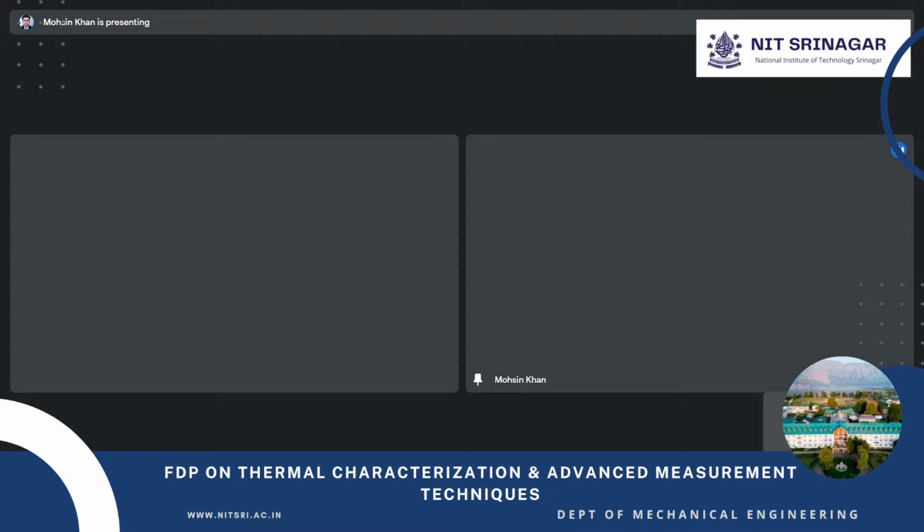This step shows the mechanical stirring, where essentially we use mechanical stirrers or magnetic stirrers to perform the stirring operation. It has been found that stirring alone is not effective, so we need some add-on processes, which include ultrasonification. Ultrasonification is essentially subjecting the mixture to sonication, which is done either by an ultrasonic bath or by a probe sonicator. The advantage of subjecting the mixture to ultrasonification is that it ensures high stability and a uniform dispersion, and the particles are uniformly distributed. And finally, we have a nanofluid with us. So again, this is a schematic wherein we show how we have prepared the nanofluids.